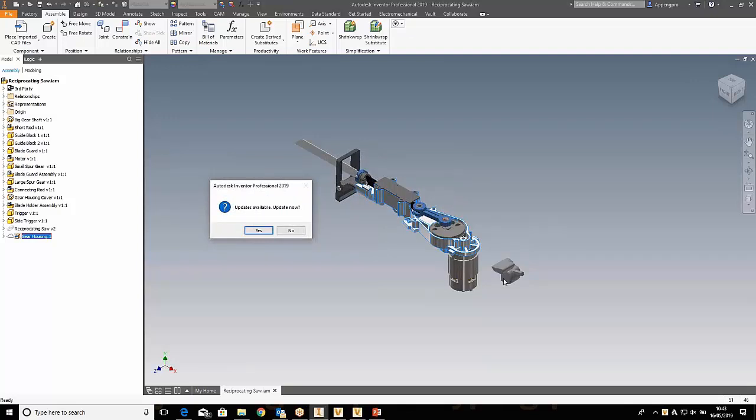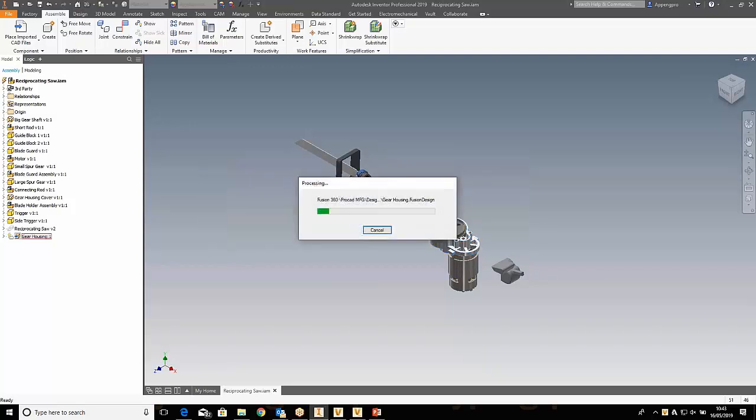So again, I really should focus in on this part here. You can take a quick look at this web. When I come along here and select yes, what I'm really doing is accepting those changes from Fusion Team that Dara has subsequently made. So if I click yes, you can see we're getting a re-download of all our files. You can see I get an update here, and it's really just doing a download of that particular version for us.